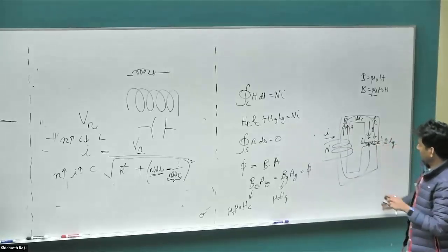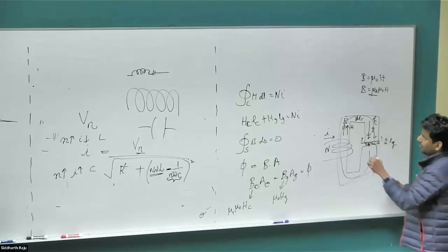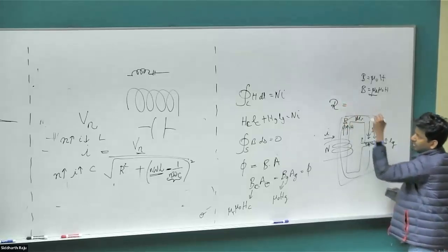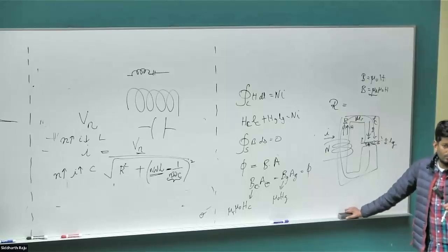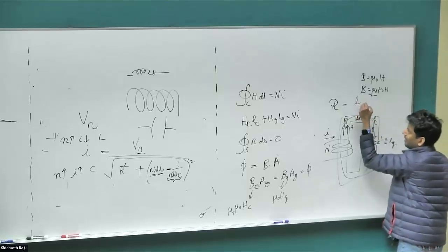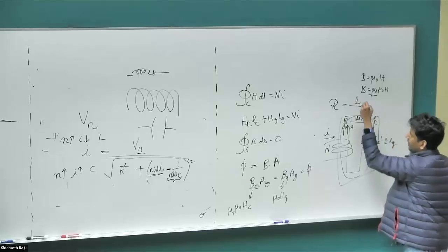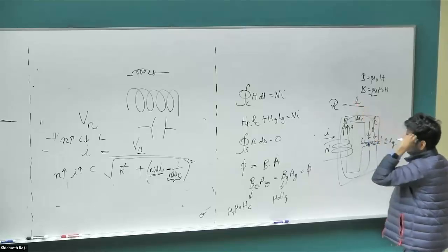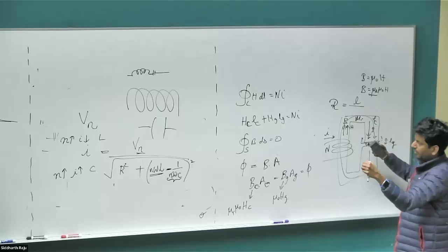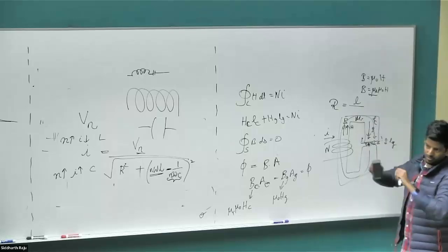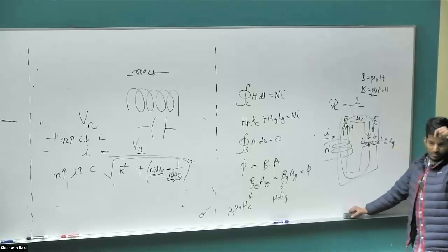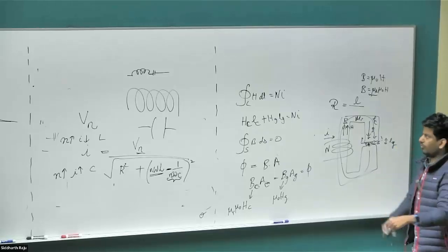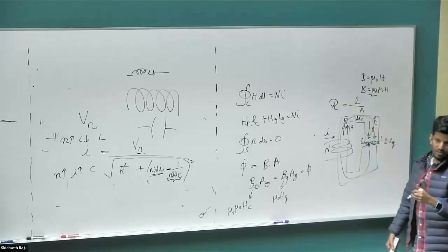So how do we get the reluctance? Anybody remember the formula for the reluctance of the air gap? Oh, yeah. So it has the same formula as resistance. So resistance of a wire would be, don't memorize it. If a wire has longer length, the resistance is going to be longer. So the length has to be on the numerator. Straightforward. If the cross-sectional area of the conductor increases, then the resistance starts to drop because the current has more pathway to flow through. So the area has to be in the denominator.